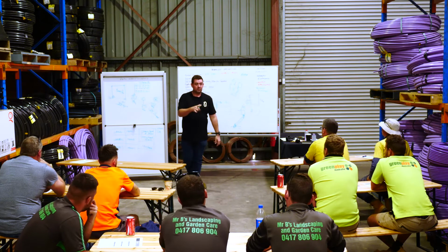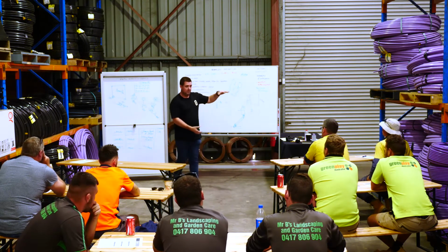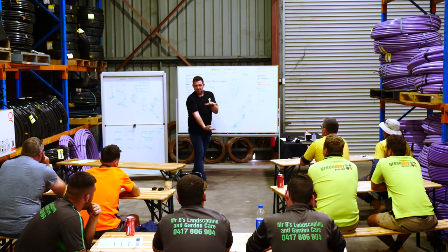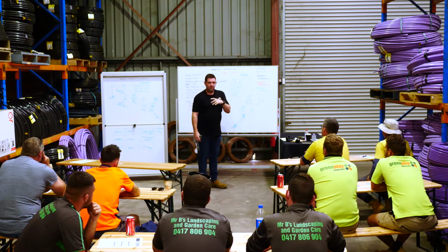When we do a pressure versus flow test commercially, I use a wheelie bin because there's so much water coming out. We're squirting like 100 litres a minute into a wheelie bin. You're just not going to do a bucket test like you've seen. So having that would be helpful.